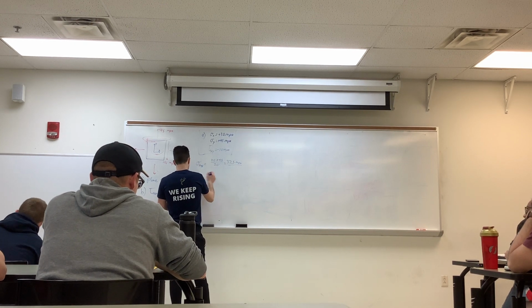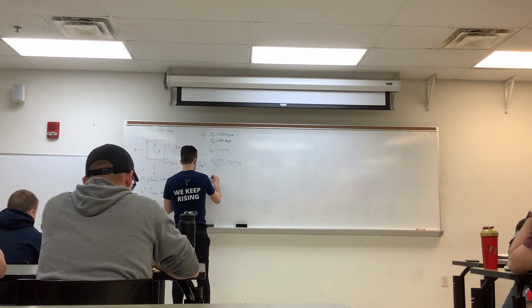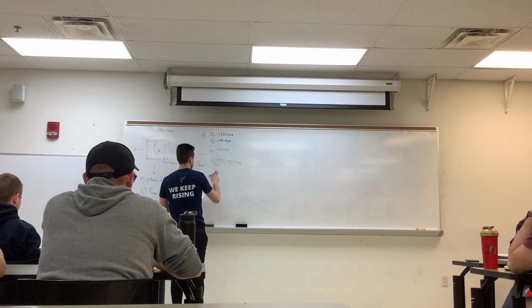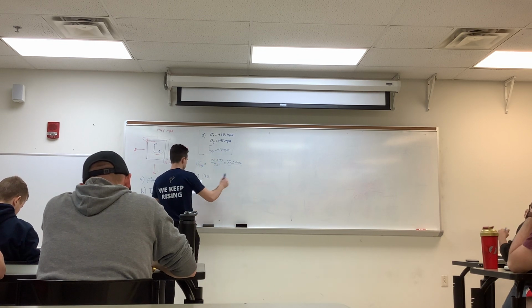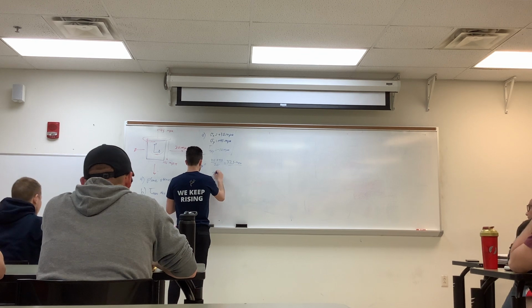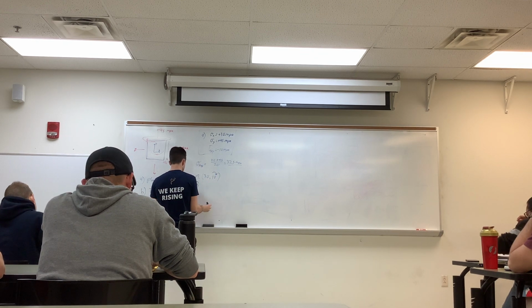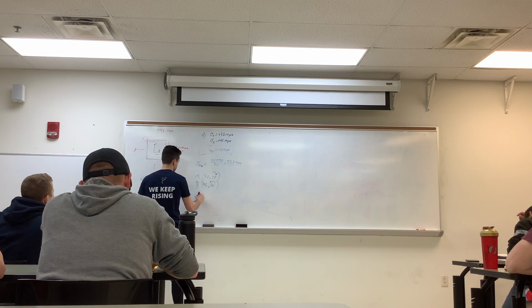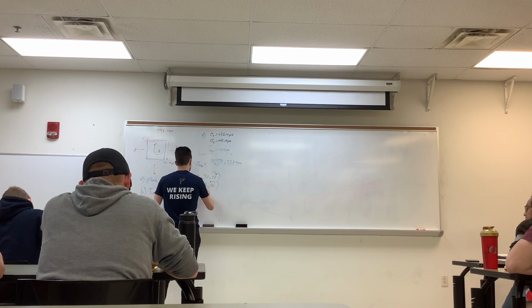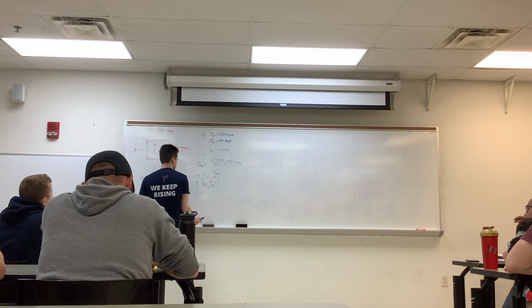So for point A, we have it as positive 30, and then since the shear is negative here, the first one will be 10 going clockwise, plus an MPa. So point B, similarly, we have 45, 10 going counterclockwise. Then we have our center, or point C, which is at 37.5 when the shear is 0.